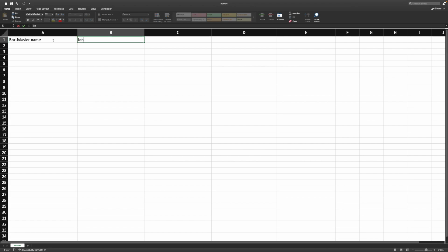And since it sets the name attribute, we add a .name to the column header. Next column sets the length model parameter, and since we are setting the expression value, we use length.expression. We do the same thing for width and height model parameters. Since sketch text objects cannot reference parameters in Fusion 360, we refer to this object by its text value with the text attribute, in this case text1.text.